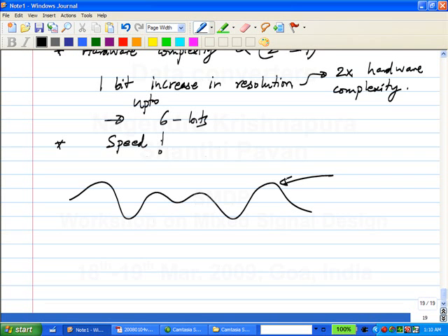So it turns out that one way of doing it is to basically write these things so far away that it's very clear if the magnetic domain is oriented in this direction or in the opposite direction. But unfortunately that means that the density with which you can pack information becomes very poor, okay. So what people do is you try to pack as much information as possible. In other words, the separation between the directions of the domains is actually very, very small, okay, and this way you can pack a lot of information, right, and you use electronics and DSP to be able to look at these small differences and then still be able to figure out what data was written, right.